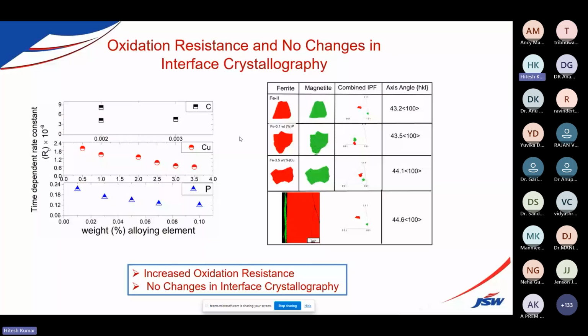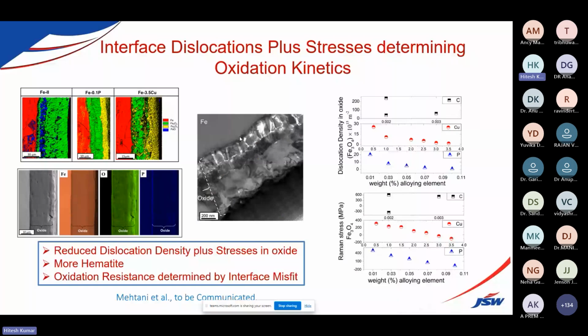In EBSD, there is a way to take out one particular phase and make it a different substructure, a sub-article, and then find out the grain size of that particular phase. Let's suppose we talk about this one. Here I can choose only the magnetite, and the others, ferrite and the rest, will be converted to black.